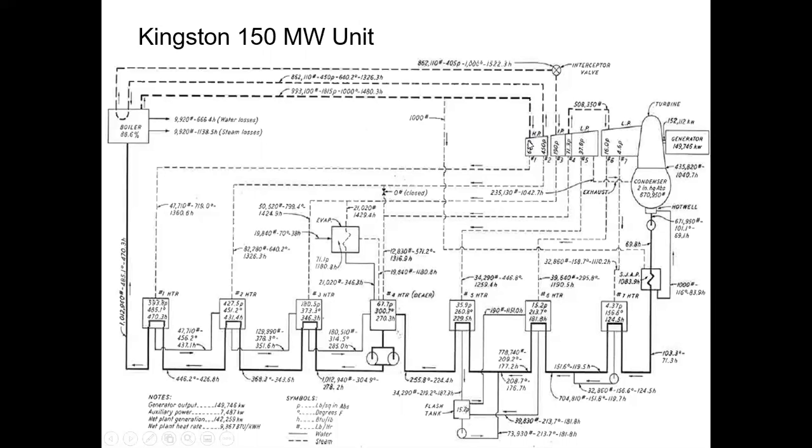Goes into a high pressure turbine. We come out, we have all these extractions. These are extractions where steam goes partially through the turbine and then it's pulled out. So the first extraction, you come down here and it goes to feed water heater.